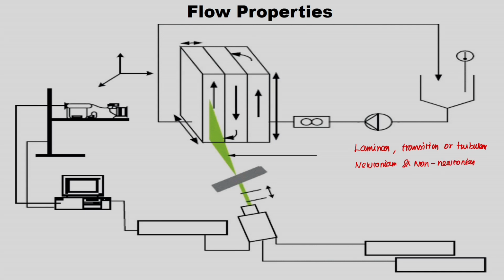Right. So, when we use such cases, I have also mentioned, for example, you have an electrode here. Based on the flow consistency index, what may happen is the fluid layer which is next to the electrodes will not move faster. In that case, it may get heated at a higher rate and cause overcooking or over processing. This can be avoided if we know the flow properties inside the ohmic heating column well.